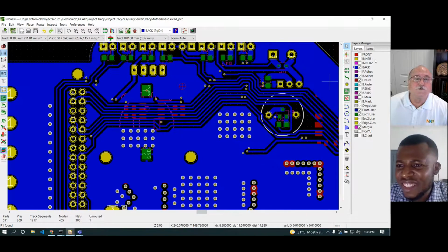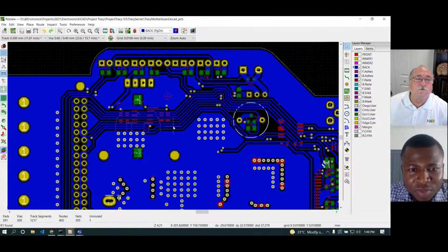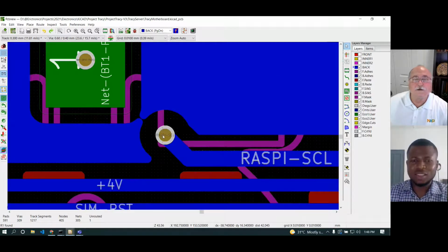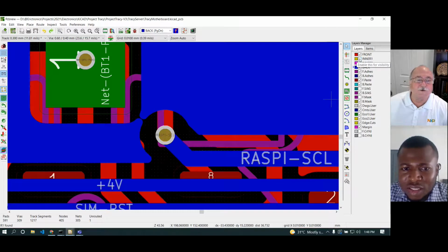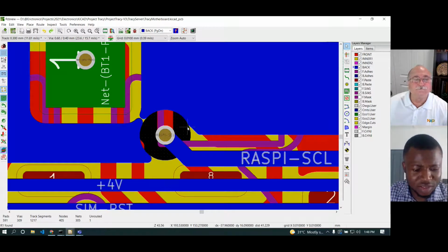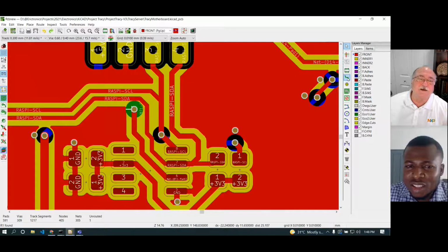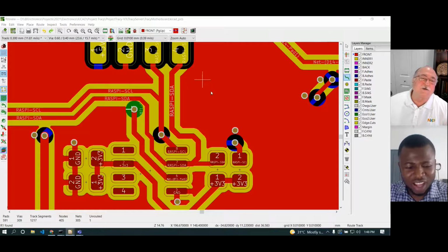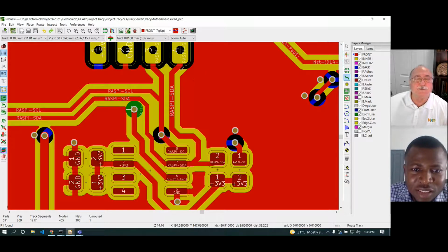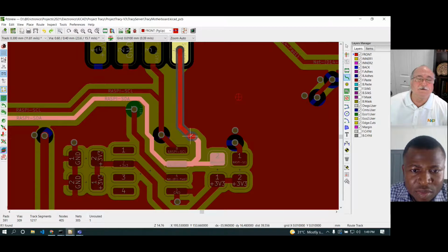Okay, great. So right there, to the upper right of your cursor, there's another orphan via. That one's an orphan as well. It gets there okay, but it doesn't go back down into the board stack. This is where sometimes you might have to move things around, and there's plenty of room to move that. Raspberry SDA can be pushed up and to the right, and that will leave you plenty of room for the ground via to make the other signal happy.